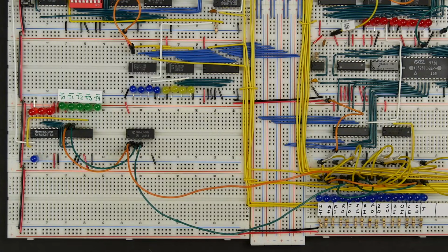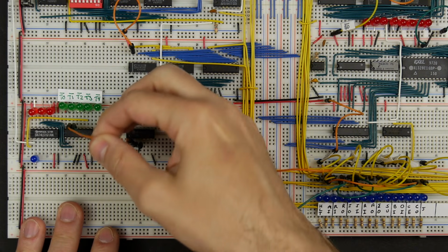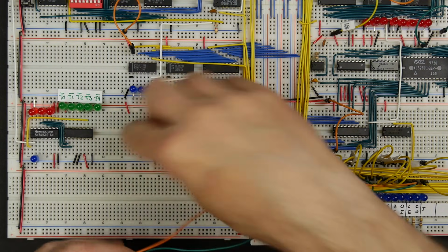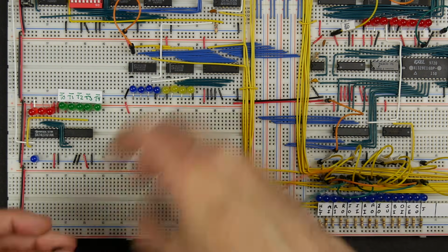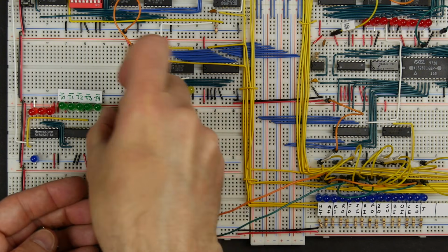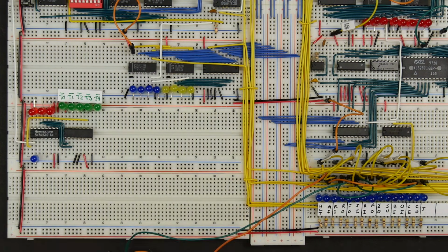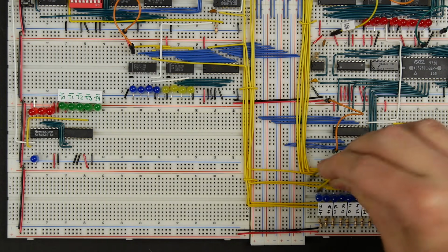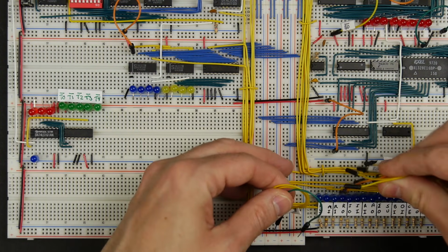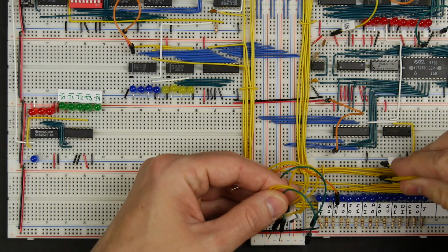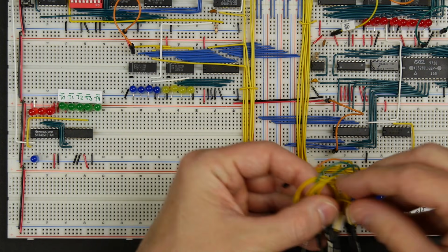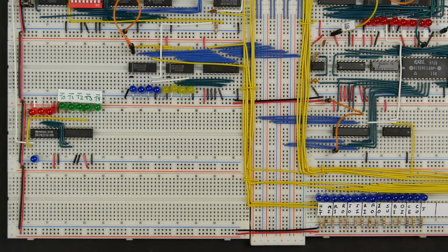So now to actually build that, to add those EEPROMs into our circuit here, first I'm going to get rid of this sort of temporary setup that I had here with this inverter. We're not going to need that, since we're going to replace all that functionality with the EEPROMs. And I'm also going to disconnect all of these jumpers that I was using to manually set the control words, because we're now going to be able to use the control logic that we're about to build. So we'll get all that out of the way.